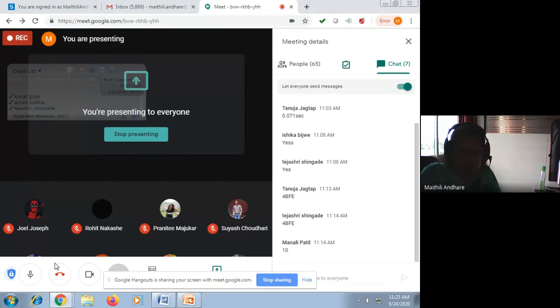That's it from my side for the timer. We have taken a number of programs and two types of calculations in the timer. One calculation is, if the initial value loaded in the timer is already given, how much delay is generated from that value, and the procedure to calculate the same. The next is, if I want some delay generation, that is X amount of delay, 5 millisecond, 10 millisecond, how much value is to be loaded in the timer register to generate that delay. These two important calculations we have seen.